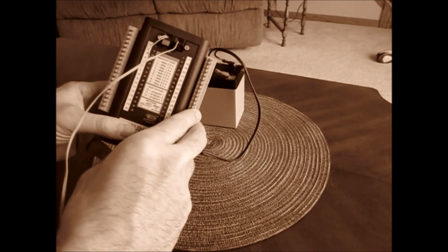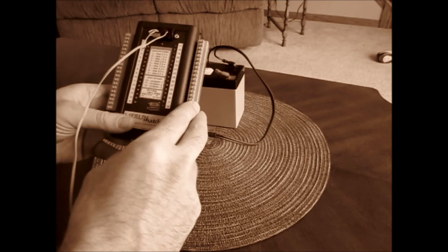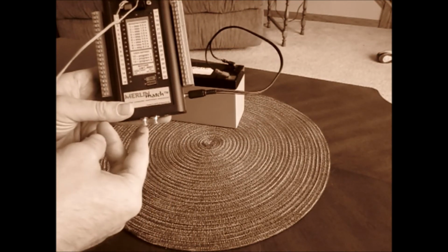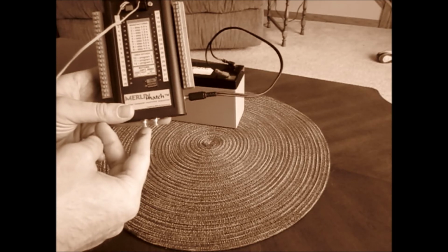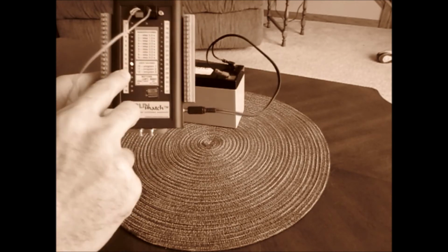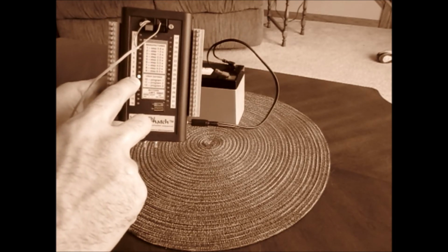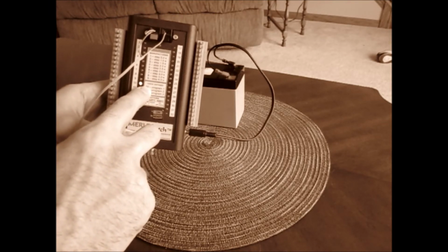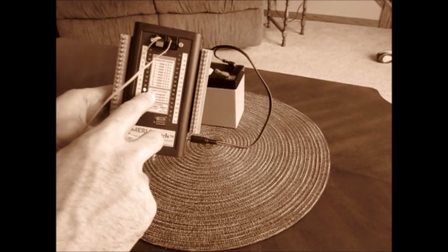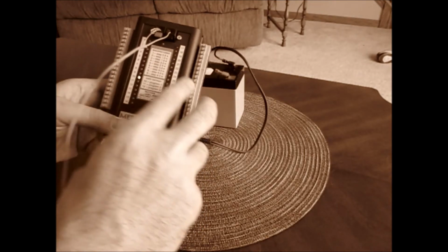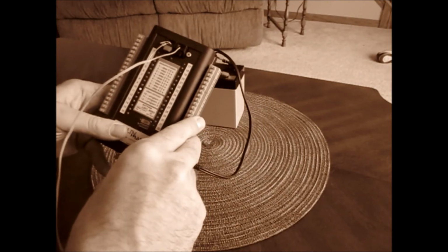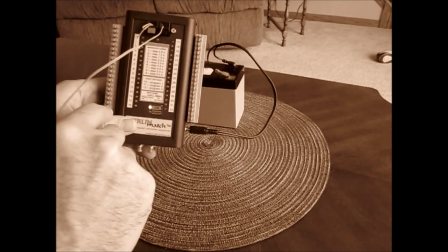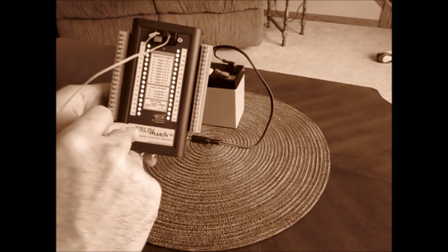Now, we're going to want to find out what program this is set to. So when you're facing the MerlinMatch, you push the little red button here on the left once. You see Q10 indicating program 10 is lit. Program 10 is the user-defined one that we set up in the video just before. So that's what we want. We're going to say, yeah, we want it. Goes ahead and it redoes its continuity checks, saying that we don't have any good E-matches plugged in.